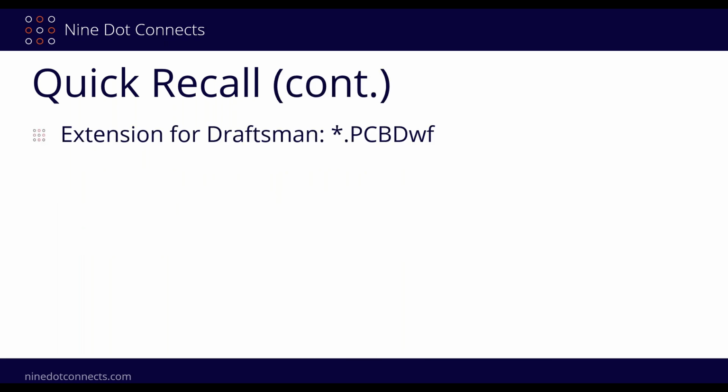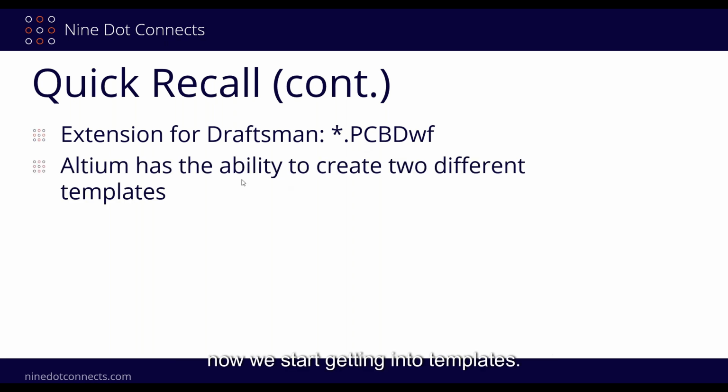Okay, just a couple of extensions. There's a lot of extensions that get thrown around here, so let's take a look at these, and I'll try not to rush through them because they're new to the eye, right? We're kind of used to SchDoc and PcbDoc, but these, if you look at them, make some sense, but at the same time there's a newness to them. So getting your head wrapped around them may take a little while. But the general extension for anything that's Draftsman, so you do File, New, Draftsman, is going to be a PcbDwf. Okay. Now we start getting into templates.